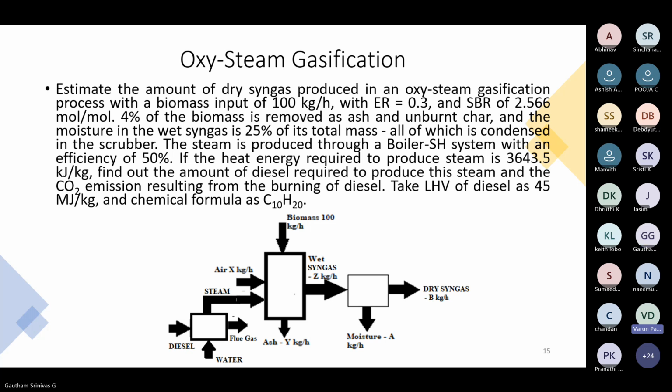And divide the molar mass of oxygen by biomass, and we'll get the stoichiometric value. Why molar mass of oxygen? Because we want to calculate how much oxygen is needed for 1 kg of biomass to burn.